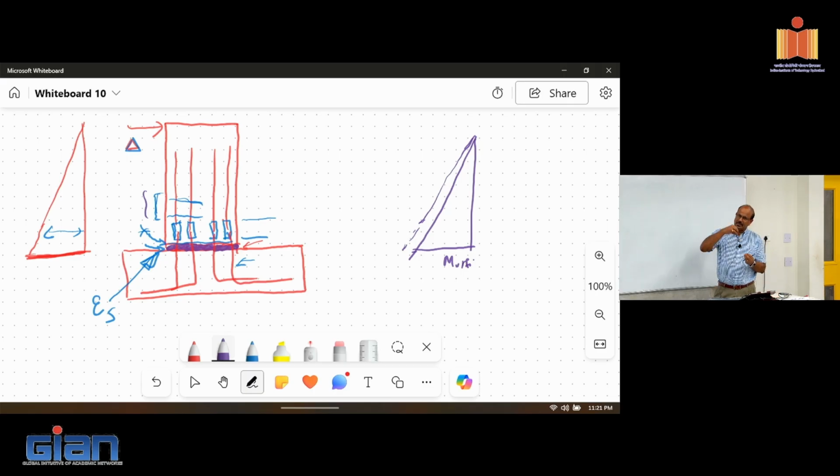Once you have large strain developing at the interface, their modulus also goes down because of the inelastic strain. So they can easily shear, and laterally they don't have much strength. You have a crack, plus their modulus is lower, so they tended to go sideways. There was a lot of slippage. So yes, the length matters.